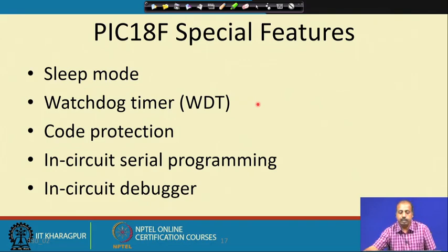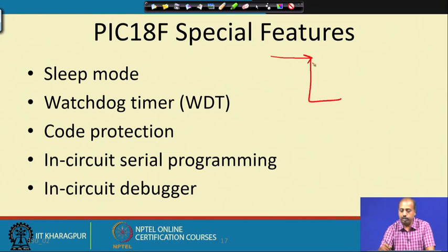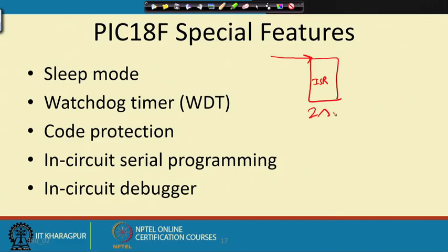It is like this. Suppose we have some interrupt, and if that interrupt occurs, the interrupt service routine has to be executed. Now, if this interrupt service routine is not complete within some predefined time, for example, for some critical operation, maybe we say that it should be over within 2 seconds, then it may be taken as a failure for the system, and some higher level activity has to be triggered.